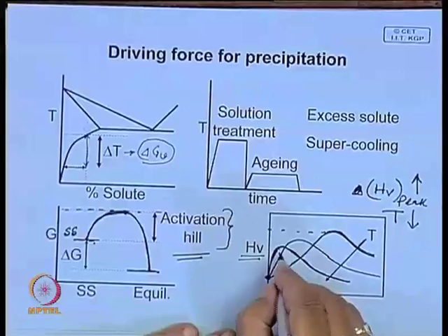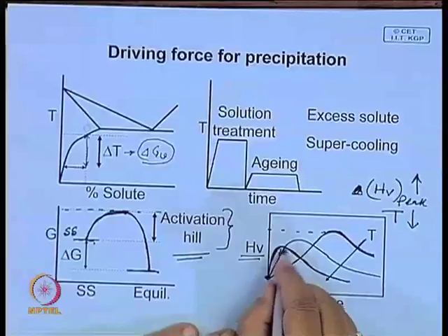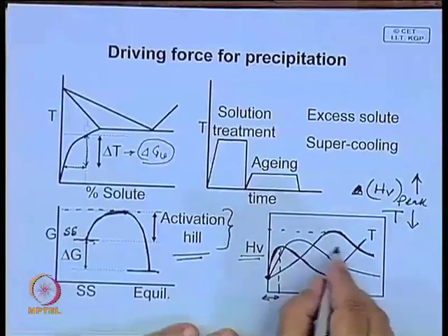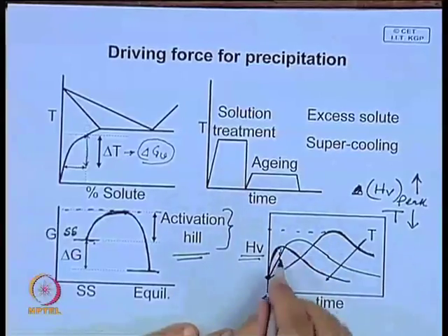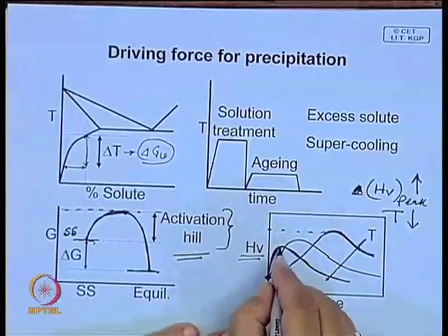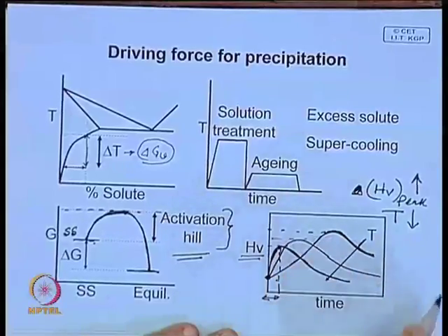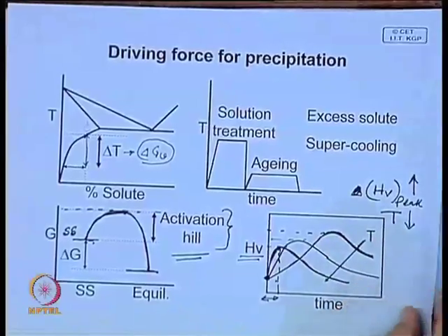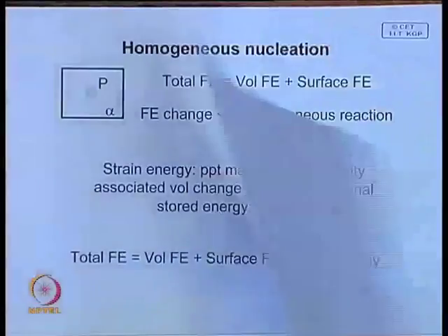and the time at which that peak hardness is reached is lower, the higher the temperature. That means the process of precipitation is faster at a higher temperature. So, therefore, the peak is attained faster, but to get the full benefit you have to optimize the aging time and temperature, so that you get an optimum strength which is usable, which has a proper application.